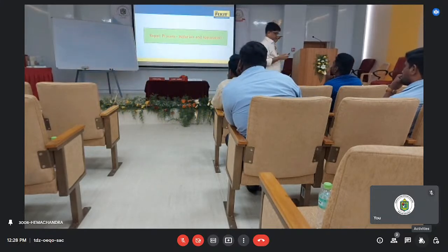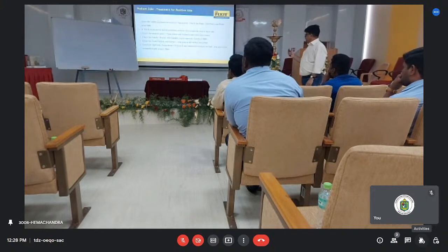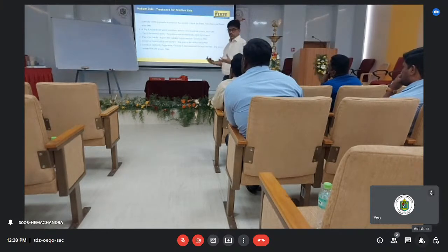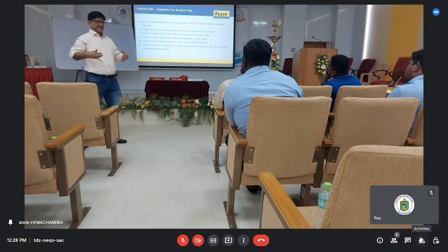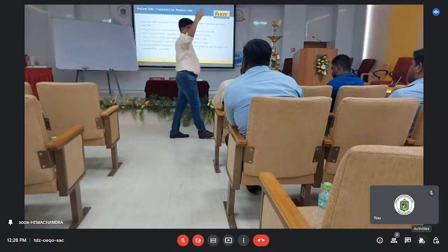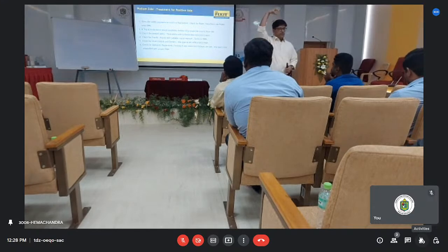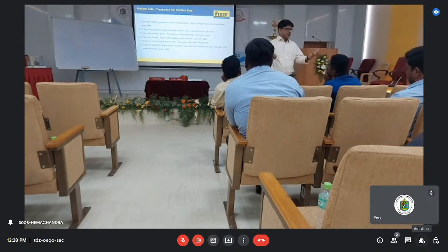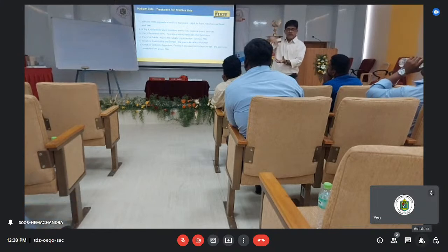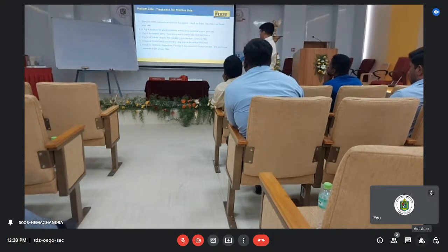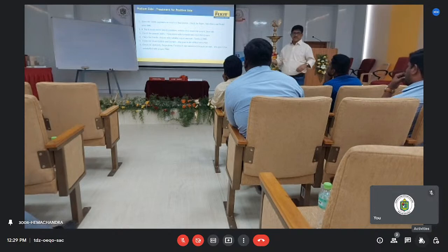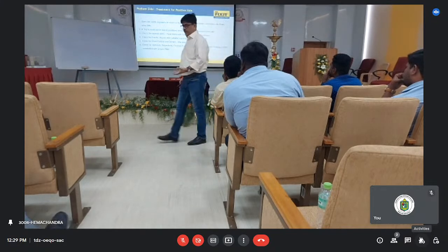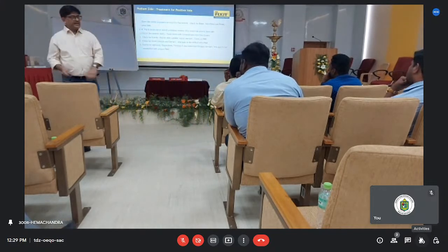Now coming to the repair process. Let us start with the podium. If it is on the podium side, I am on the positive side. If I have seen that there is a problem somewhere, then I can do it from the top, because I can put positive protection on a podium, since water is coming from the top, your rainwater or standing water. So we can definitely open the topping segments, check for the slope and soundness, and wherever it is not sound, we can repair those areas with the proper repair material, polymer modified mortars or similar.